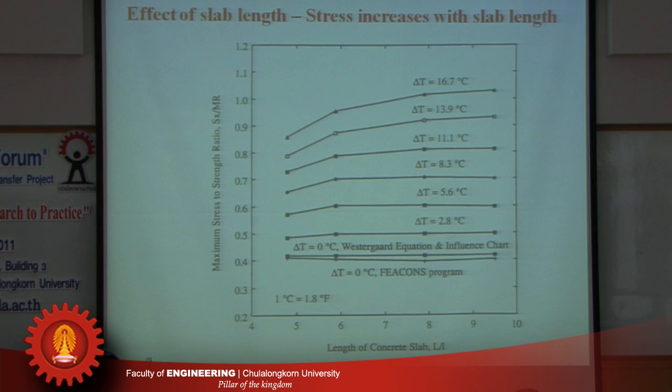And also the slab length now has a great effect, while before it had no effect. Here is maximum stress versus slab length. When there's zero temperature differential, it's basically flat. Slab length has no effect, but when we have a temperature differential, the higher the slab length, the higher the stress would be. And also, the temperature differential has a great effect. So we need to know what the temperature differential for the region might be.